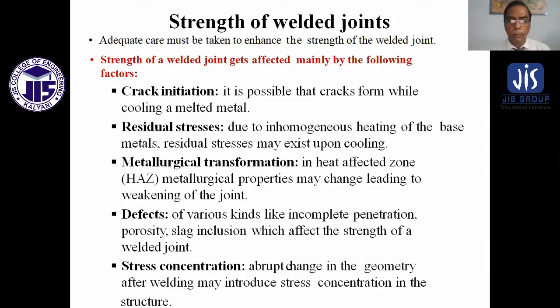Defects of various kinds, like incomplete penetration, porosity, slag inclusions, blowholes, affect the strength of welded joints. Stress concentration: an abrupt change in the geometry after welding may introduce stress concentration in the structure.